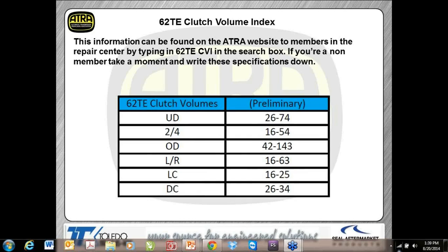Now, once we get the direct clutch off, we want to disassemble it. There's a tapered snap ring, as you can see right here, and it's a bevel type snap ring. We want to have the dish facing up, just like we would on most of the cushion plates that we see in other transmissions. So the dish faces up on that. Then you'll find a couple of bearings in there, and first thing you're going to notice is the clutches in this assembly are single-sided clutches.